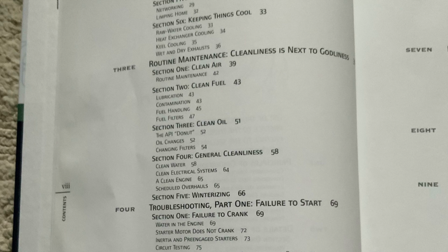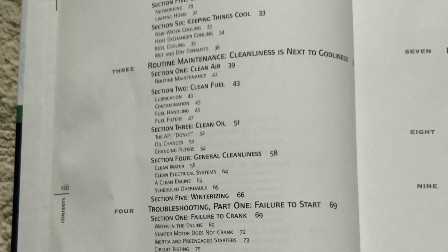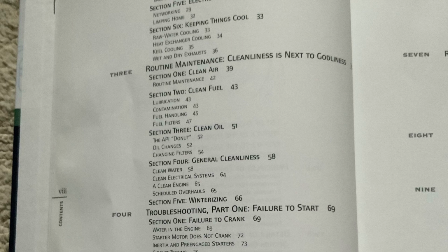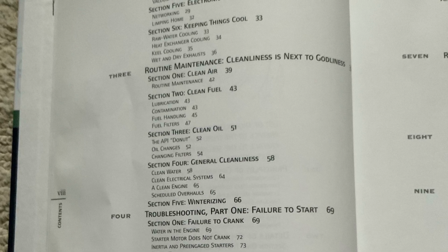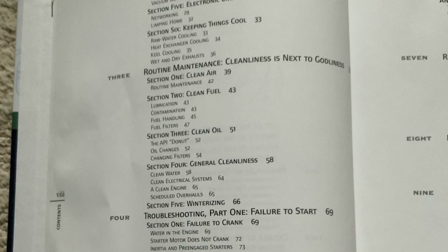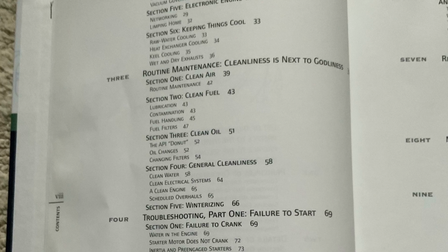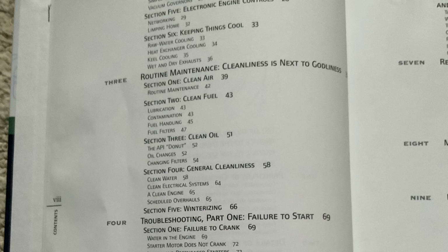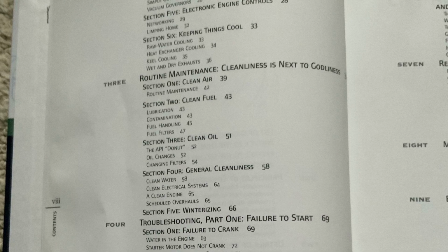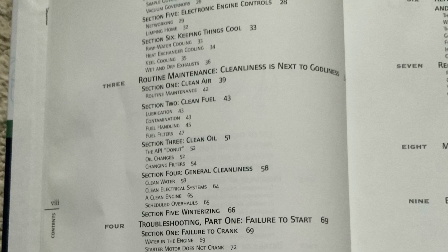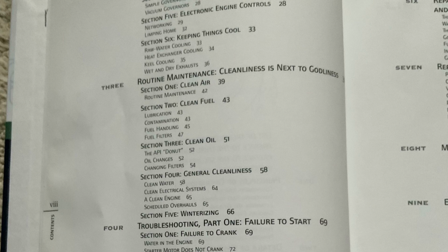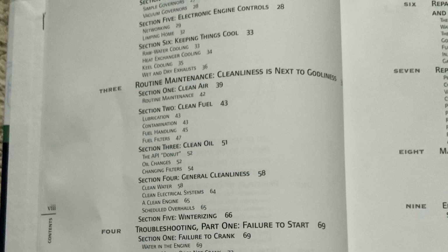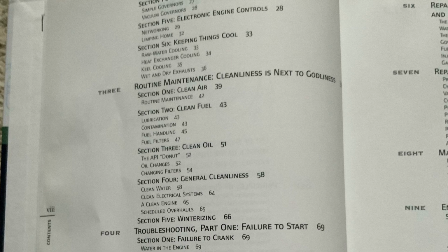This is much higher than the average gasoline engine's compression ratio of 7:1 to 9:1. The lower compression ratios of gasoline engines produce lower cylinder pressures and temperatures. As a consequence, the ignition temperature of gasoline is not reached through compression, and the gas-air mixture has to be ignited by an independent source, a spark. Hence, the designation spark ignition for gasoline engines.